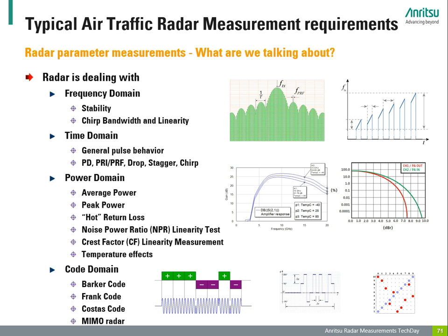As already said beforehand in the other chapters, radar is dealing with signals that need investigation in the time and frequency domain. So far, we have just discussed simple pulse durations and repetition rates, but the radar art is based on a complex orchestration of different PDs and PRFs. Pulse compression is just one way of tweaking the radar system to achieve the desired goals.